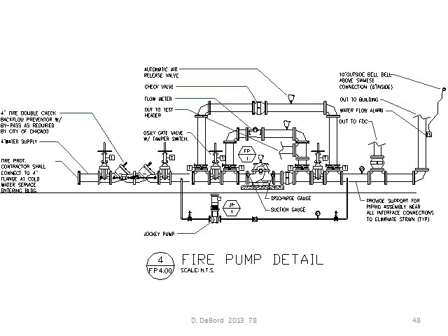This is a fire pump detail. You can see the incoming service is actually installed by the plumbing contractor. Normally the double check backflow preventer is installed by the plumbing contractor, but it might be purchased by the fire protection. That's something that could be worked out on different projects.